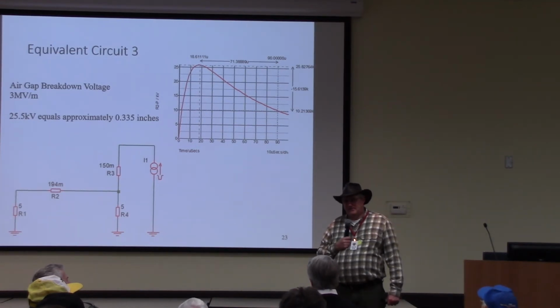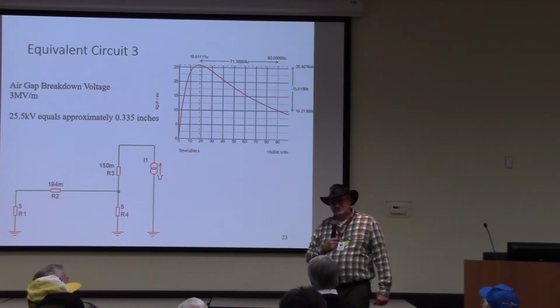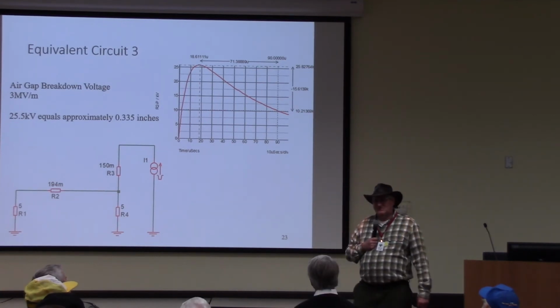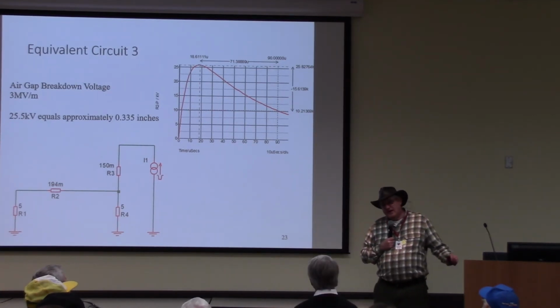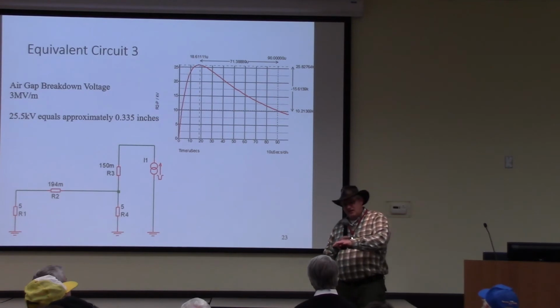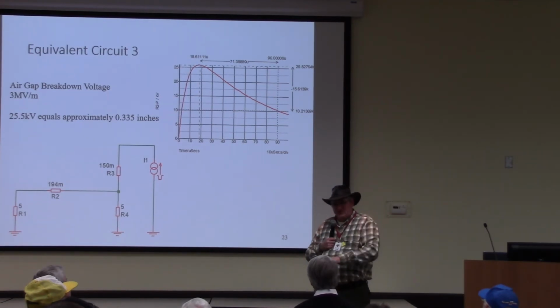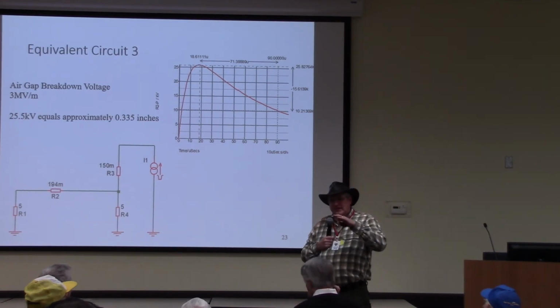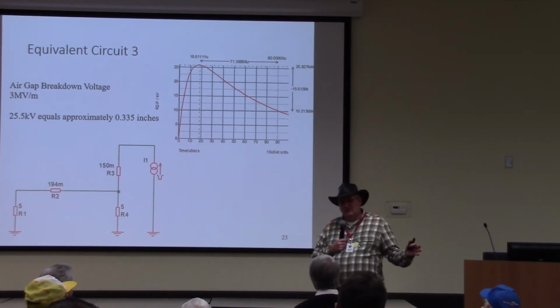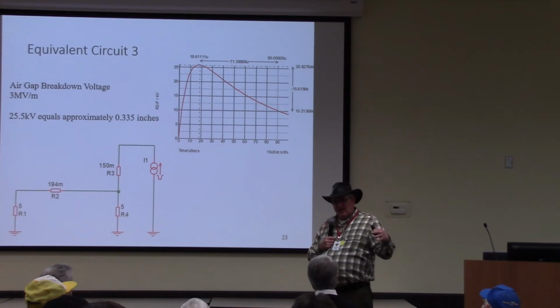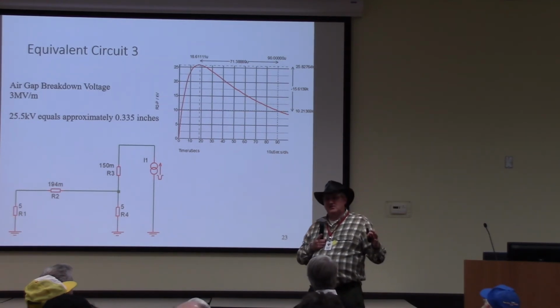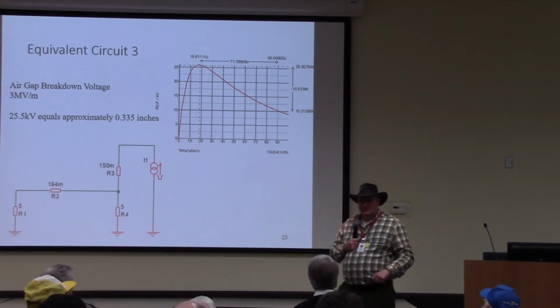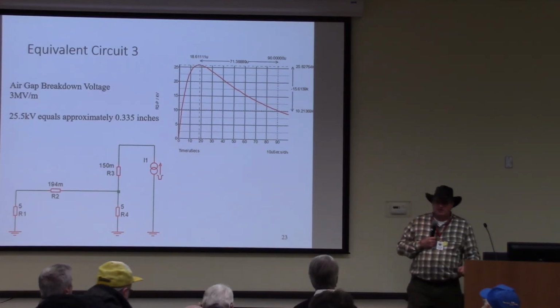All my equipment's tied to that, so it's all together. Well, all being together like that, it'll all raise at the same potential at the same time, so you won't get arcing in between those. But anything that's close by that isn't tied to that, you'll get a voltage potential across there, and that's where your arc comes, if you jump over to the other parts of your house.